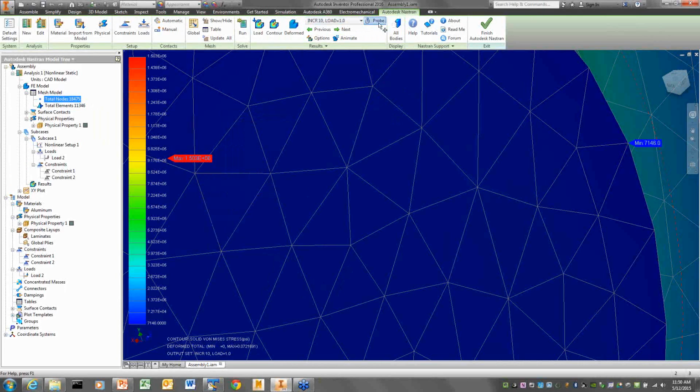Okay. So we did have another question come in. We're interested in extracting forces versus displacements as a graph from a nonlinear simulation. Displacements are certainly what you will get. If you do forces, unfortunately, when you run forces, they're element forces, not nodal forces.